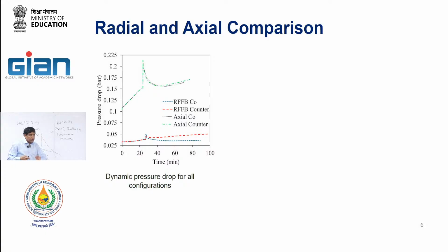Right. So up to here, basically at this point, we are capturing the CO2. Because I am capturing the CO2, the flue gas flow rate is lowered. So a lesser amount of flue gas is flowing through the system. As it is adsorbing, or the CO2 has to go through a longer path length, the pressure drop keeps increasing. Up to this is the adsorption cycle.